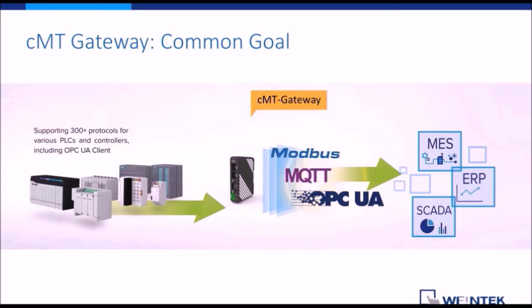Okay, so MQTT basically now is the IoT protocol, and OPC UA is the emerging industrial interoperability standard. So these are probably the two key software features that our gateway works with. In addition, we also have Modbus server on our gateway, simply because Modbus has been the most popular fieldbus protocol for the industry. So our gateway will support these three protocols to integrate your ERP system, your MES system, or